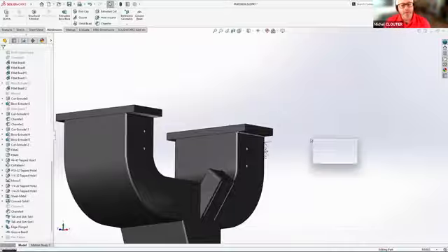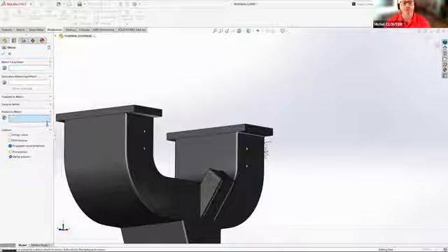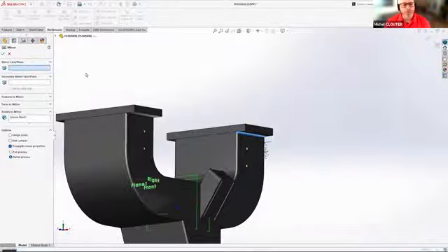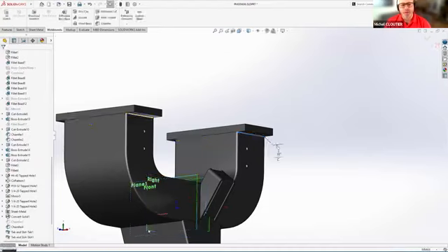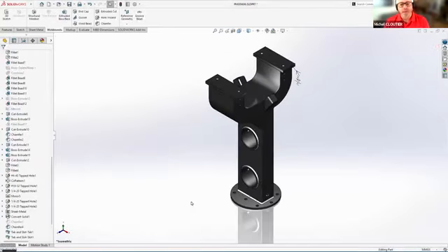And also those groove beads are just like any other features now, meaning that I can also use them in mirror commands, for example. So here I've got my groove bead. I created just one, but it's going to be repeated symmetrically on both sides. So here we go. I just do a mirror feature and I've got everything ready to go.